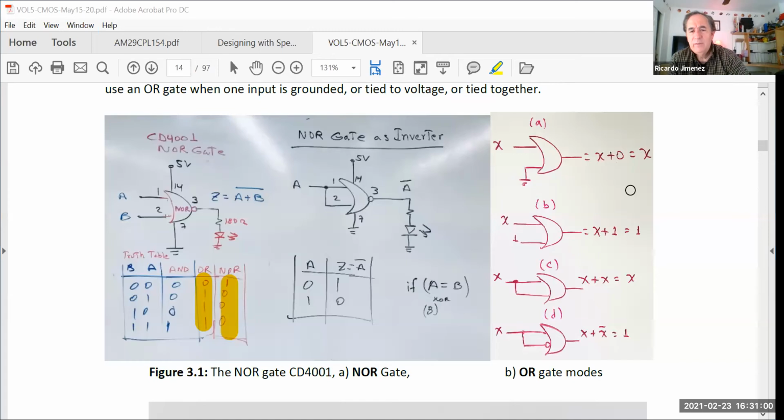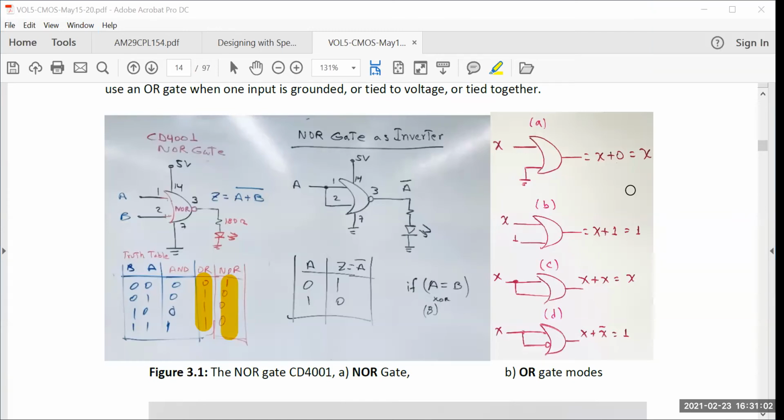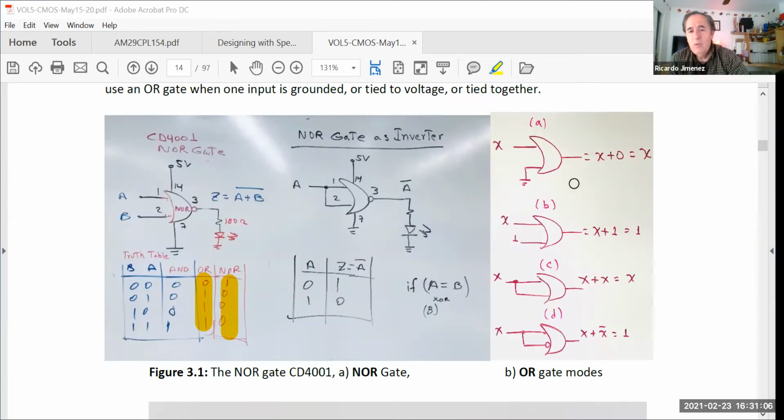And you might be asking yourself, what is the purpose of having the output following the input if I have an x here and an x there? Because many times you need this variable x to have a high impedance at the input and a low impedance right here. That means that you can drive other devices. So you can use it as a driver.